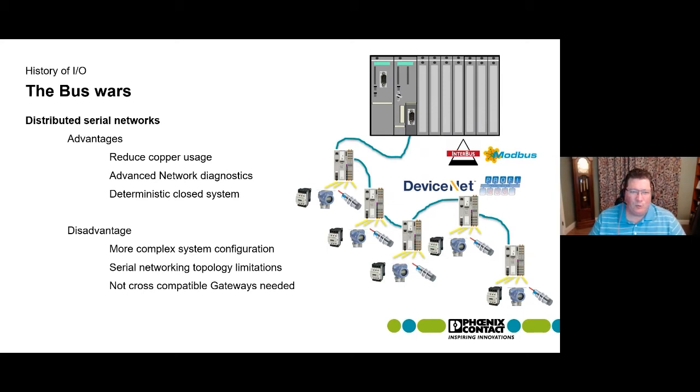In the end, technically, the PLC is still doing its same function. It's still looking at the raw data from each of these bits and words, depending on whether it's digital or analog modules, and it's still performing the exact same function. We just pulled out an I/O card and replaced it with a new card that has a little bit of smarts in it that can actually handle the communications to these end devices. This gave an advantage for cabling.